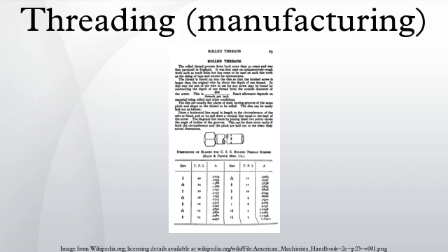The tooling used for thread milling can be solid or indexable. For internal threads, solid cutters are generally limited to holes larger than 6 mm, and indexable internal thread cutting tools are limited to holes larger than 12 mm. The advantage is that when the insert wears out it is easily and more cost-effectively replaced. The disadvantage is the cycle time is generally longer than solid tools.